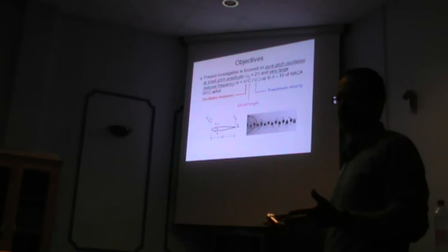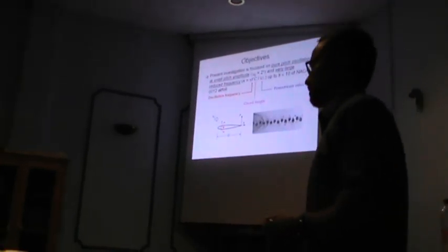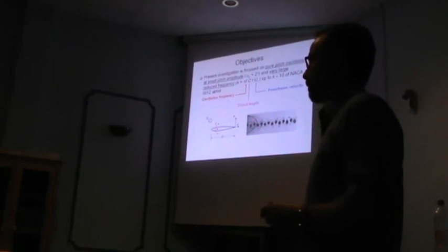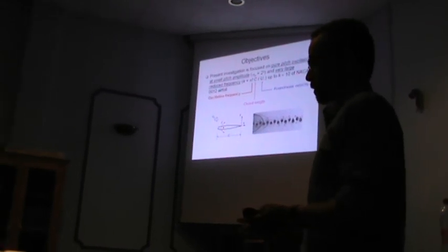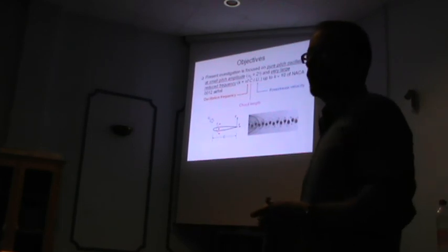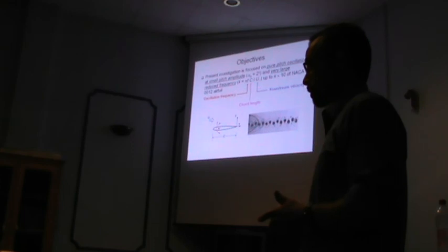This is a practical cooling problem, with film cooling and film heating. This is a different problem, where you're dealing with a more practical problem. If you have ice accumulation, of course, that will change the shape of the airfoil and will change the aerodynamics. So it will change depending on the shape, and you have to deal with the shape in this case.